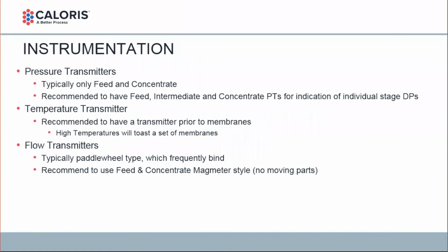Instrumentation for pressure transmitters: I'm typically seeing only the feed and concentrate used. We would recommend feed, intermediate, and concentrate pressure transmitters for the indication of individual stage DPs.